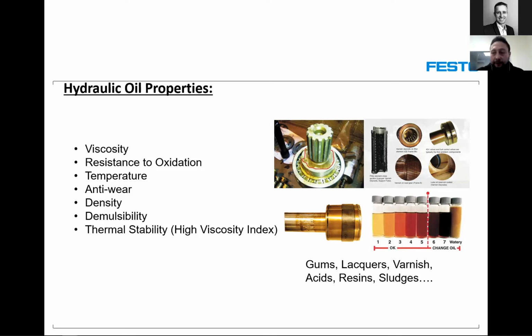Remember, oil will flow through a pipe and there will be friction in that pipe, and the oil must be able to withstand a certain amount of friction while it is moving through a valve and so on. Other things you need to look at are corrosion resistance and air release properties, as well as chemical resistance, and make sure that the oil you are using is hydrolytically stable.